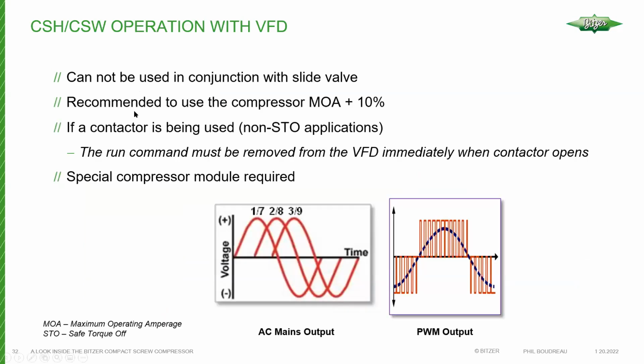It's also important to note that the VFD should never be used in conjunction with the slide valve. Okay, keep in mind this is a refrigerant cooled motor, and if you're driving the slide valve down to, the worst case scenario, let's say we're driving that down to 25%, and then you're going to slow the compressor down to 25 hertz. We get to a point where oil lubrication becomes an issue. We have insufficient refrigerant to cool the motor. All sorts of problems.